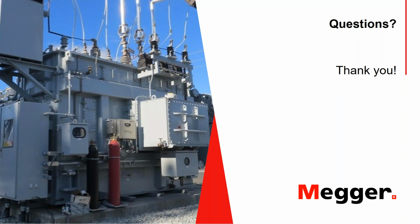All right, thank you, Dinesh. Daniel, can I use a low resistance meter to perform this measurement on small transformers? Okay, very important question. The short answer is no, it is not recommended. We at Megger get that question asked a lot because we offer a wide range of low resistance ohm meters.